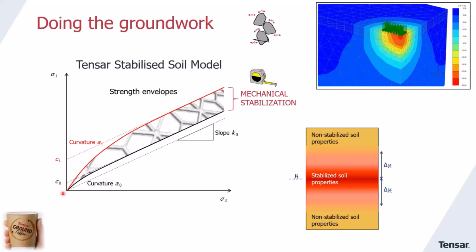And we can see that this is a nonlinear connection between those two. When we apply a Tensar geogrid in granular material, using the extensive large aperture triaxial cell testing, we have derived a much higher confinement of the granular material, which eventually results in the same friction angle of the fill material, but a higher mechanical confinement or cohesion.